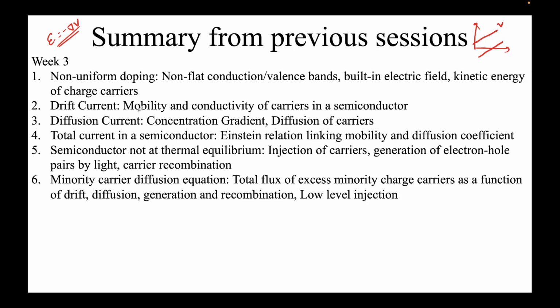And if there's a field, we introduce a term called mobility, which has something called v_d equal to mu E. So v_d is your drift velocity, mu is your mobility, E was your electric field which the carrier is facing, and it was drifting. If you apply an electric field, F equal to qE, you put F equal to effective mass times acceleration, you can solve that. Conductivity you saw as n e mu_n for electrons and p e mu_p for holes, right? And conductivity, from Ohm's law, we saw how we did.